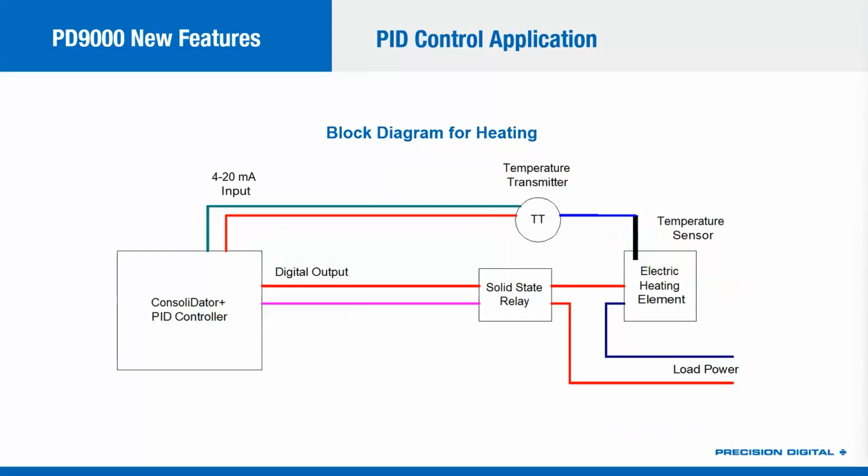So you can imagine me quickly pulsing that heating element, so it's not going to get as hot as it could possibly get. It's going to reach some kind of intermediate point. So we're going to feed it, for example, 40% power, and that's going to be as much as we need for this heating. It could be any percentage, but that's why we're pulse modulating it, to bring that heating element up to some temperature that isn't just fully on or fully off.